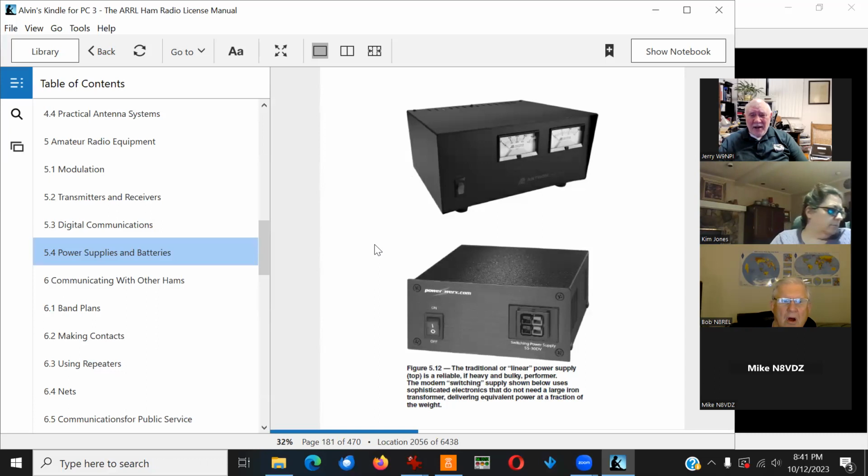Okay. The only other thing, they make a big point of this, and usually have a question there: put a fuse in the negative line from your battery. Okay. Batteries.